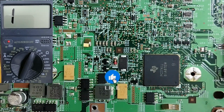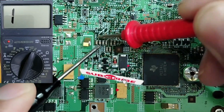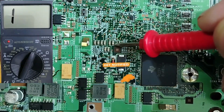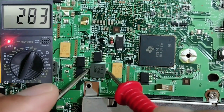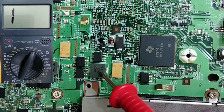Let's check ceramic capacitors. Here, for example, we have ceramic capacitors. Let's check. No continuity, no continuity, as you can see. So no continuity means these are good ceramic capacitors. For an inductor, of course, we should get continuity, as you can see, because the inductor is just a wire.